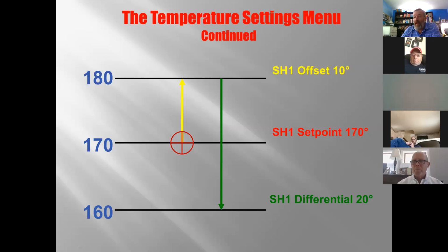And the boiler doesn't like being at 190. It kind of messes up that runway that we use to slow the boiler down and land. So 170 gets you 180. And that's how we generally will program that as the maximum.